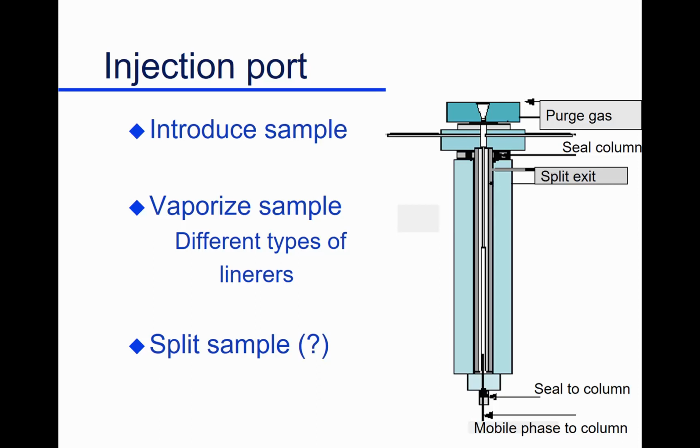Well, why do we do that? It sounds kind of wasteful, but there's various reasons. We want a high flow through the system, so we vaporize our sample. It comes down here, some goes in here, and the rest gets out of here quickly. We don't want this sitting here, over time, keep on feeding the column, feeding the column, feeding the column. Our peaks get broader, broader, broader. I want to go ahead and make my injection, whiz this through, take a little segment of that, and do our analysis. So it just keeps this clean. It doesn't allow things to build up in here. It keeps it clean because this is feeding our column down here.